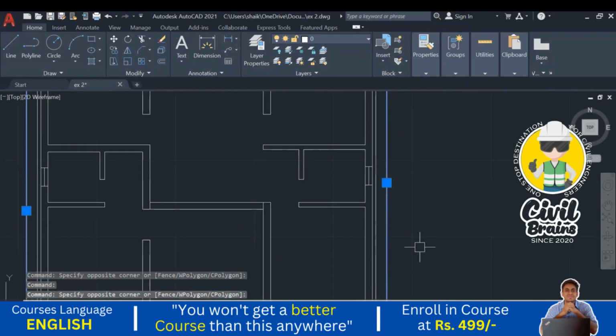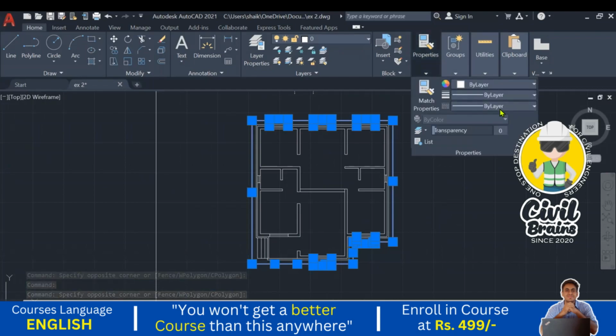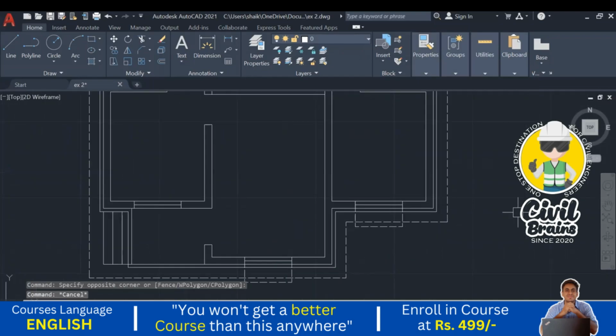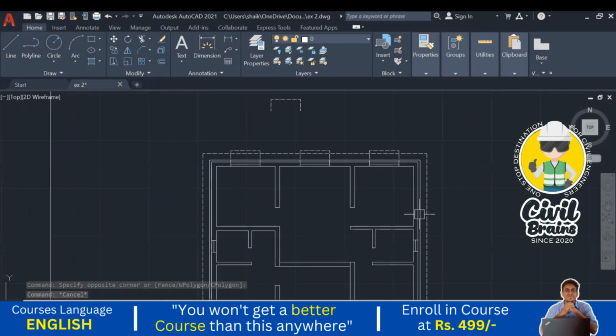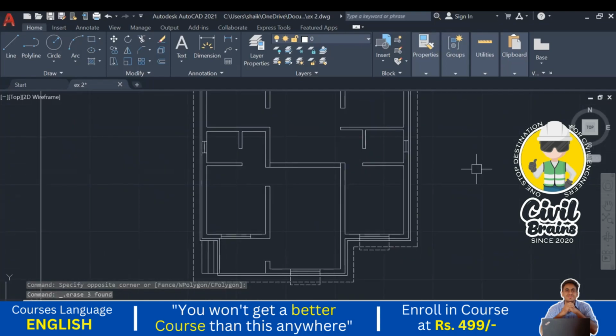Correct. I've selected everything. Go to the properties. Go here, click on this one, press escape. Now here you can see this one. All the lines, I just delete this one. All the chhajja and the slab projection I have selected as a dotted, because it is above the sill level.